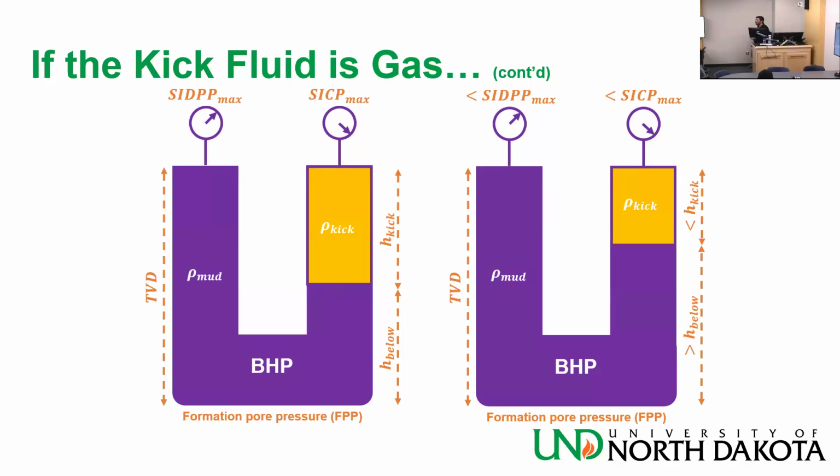I don't know if it's related. It's just a general question about kick. If I'm drilling a formation that doesn't have any fluid, and probably my mud density is not the correct one, will I have a kick since the formation doesn't have any fluid? Well, there is no fluid to enter; you're basically drilling through glass, something like that. Sand? Well, sand is likely going to have water in it. But you might drill through salt. Then you have other worries because your fluid from the well might want to go into the salt.